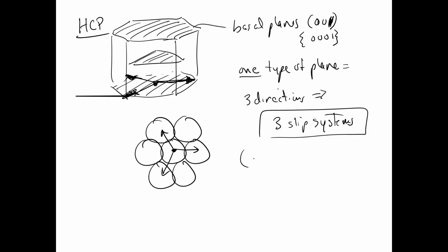So another thing we could say here is limited possibilities. And that's why the hexagonal close-packed metals are notoriously not as ductile or easy to form as BCC or FCC metals. So what are those metals? Just to remind you, those are titanium, magnesium, zinc, beryllium. There are lots of others. But titanium is a great metal, very strong, lightweight, but one of its limitations is it's not so easy to get into shapes like the other metals because there aren't very many possibilities for slip.